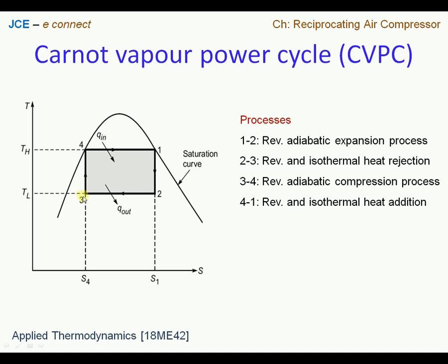And then when we look at state point number 3, we know that the process from 3 to 4 is work done by the pump. Therefore the pump is now handling a two-phase mixture region. Again, this is not desirable for a pump. A pump is designed to handle completely a liquid condition, but here we have a two-phase mixture, which is not desirable.